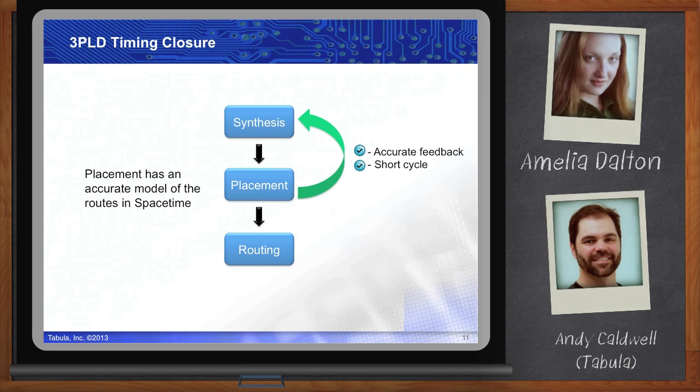So this looks to me like what has always been called physical synthesis, and we've been hearing about that for years. How is this different? Well, the timing feedback comes from a detail placement, and detail placement in a space-time fabric is a much better predictor of final timing. Okay, that's a lot to wrap my head around, Andy.